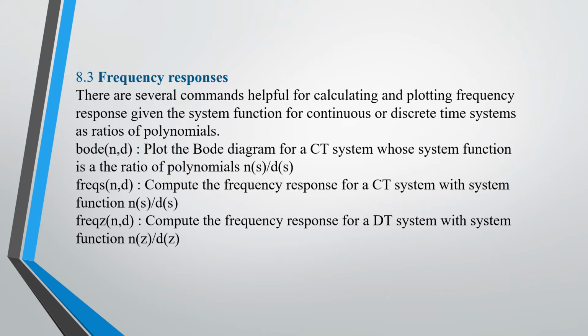For instance, bode(n, d) plots the Bode diagram for a continuous time system whose system function is a ratio of polynomials n of s divided by d of s. freqs(n, d) computes the frequency response for a continuous time system with system function n of s divided by d of s. freqz(n, d) computes the frequency response for a discrete time system with system function n of z divided by d of z.